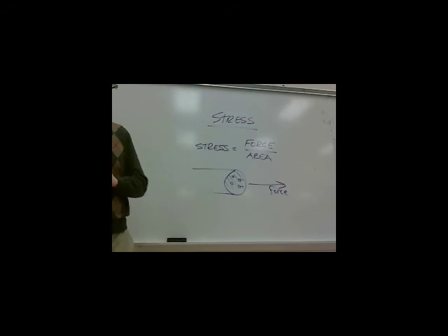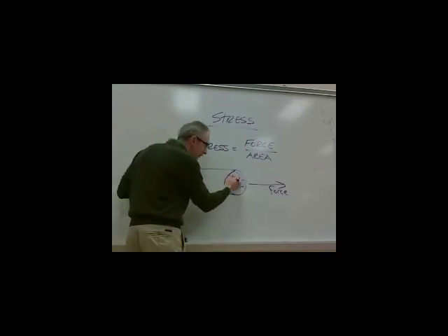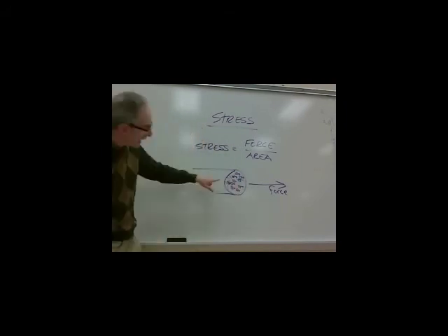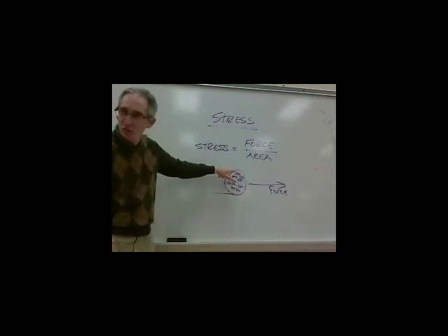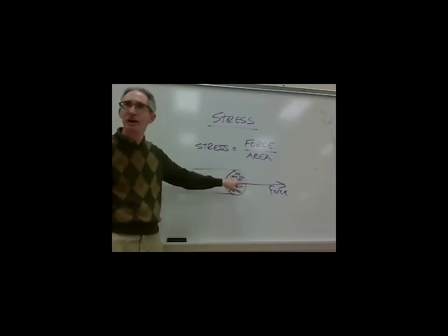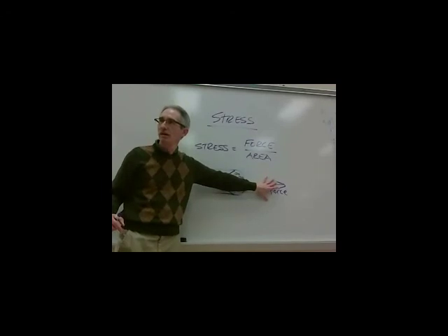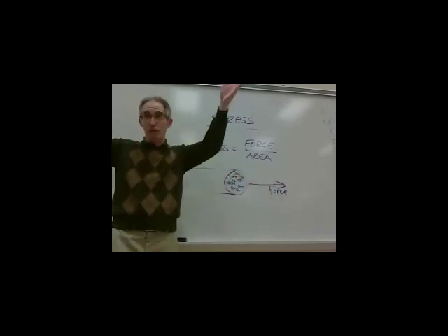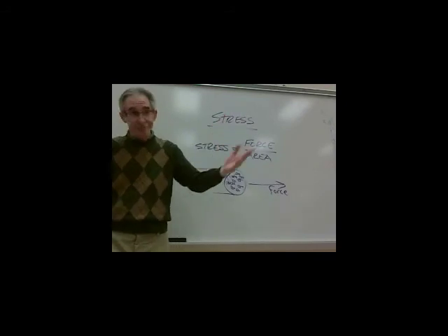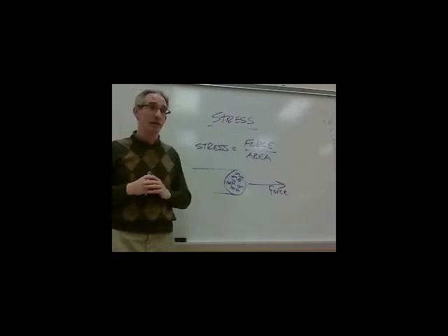Okay? So if you look at all these little pieces of area in this cross section, and you thought about the force that they all withstand, if you added up all those little forces over all those little incremental pieces of area, what would they total up to be? The total force. Okay? So all we're talking about is the total force divided by, in this case, the total cross-sectional area.